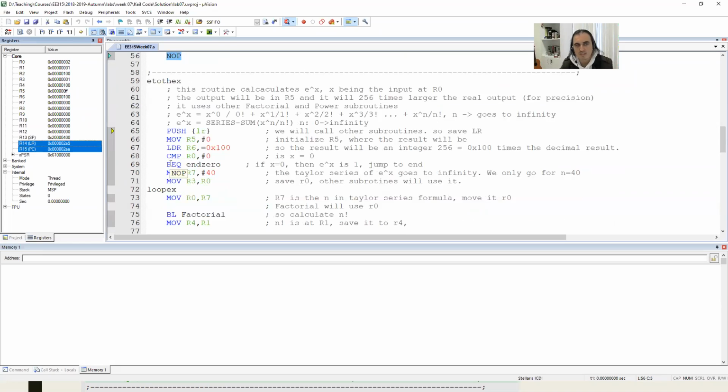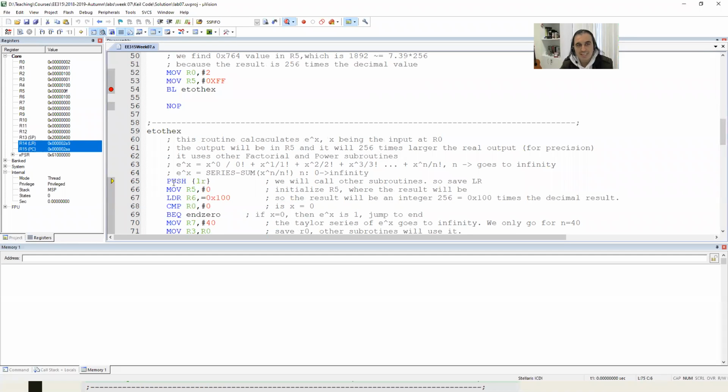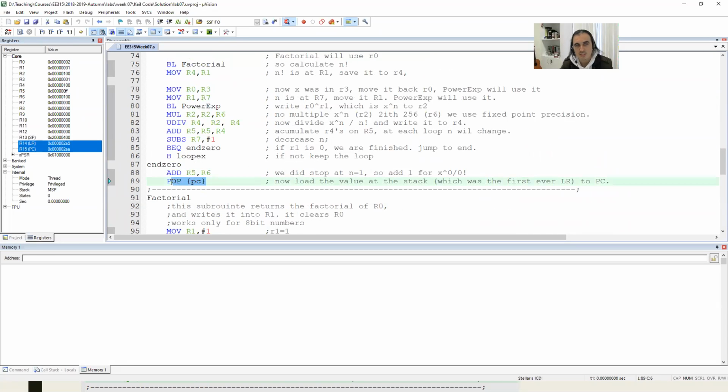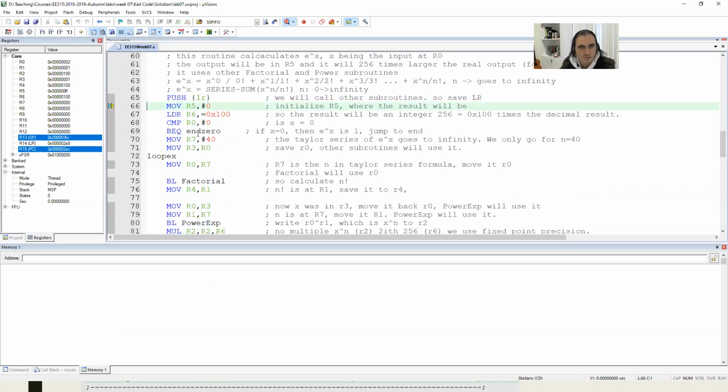But the thing is, I'm going to be calling BL inside this subroutine. I'm going to lose the LR value. That's why I push the LR value onto the stack, okay? Remember this value, guys, please. It was 2A9. Okay, we are going to pop it here to the PC. Now, okay, I've got this value. I can do F10s and just move on.